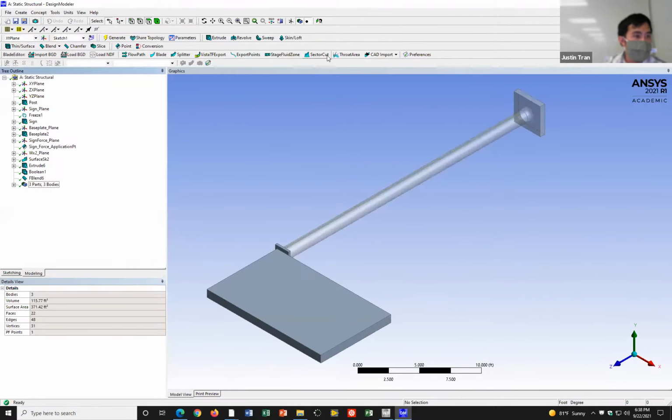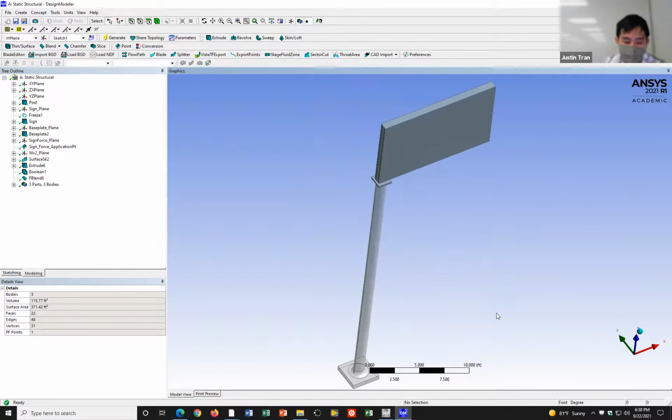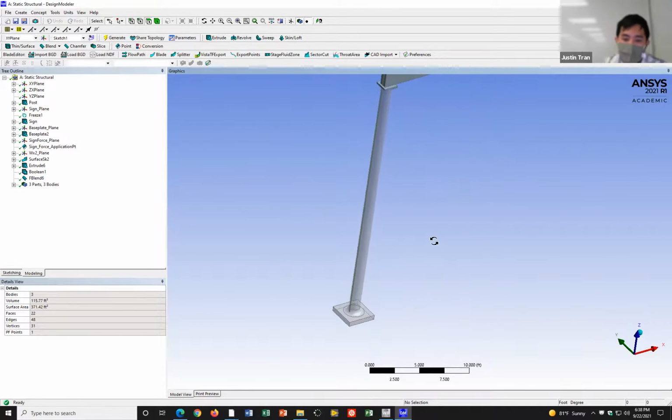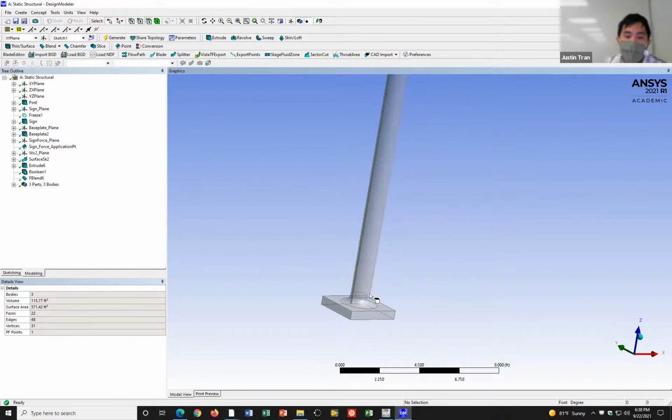Have that fillet within the ANSYS geometry? I did, yes. That's not in the screenshots in the PDF, I know, but it's something that I added recently. Right, because what was happening before is that the bottom of this post used to be just flat, and then all the stress concentration was at this edge right here, which we'll talk about later on in the class.